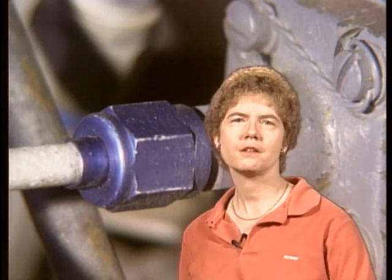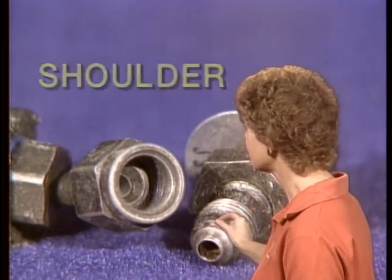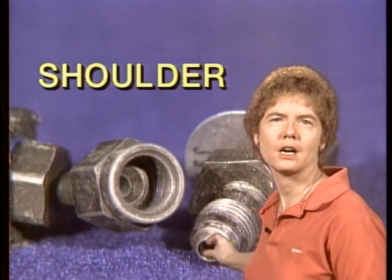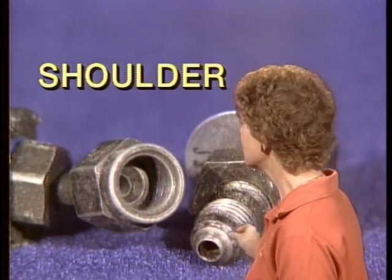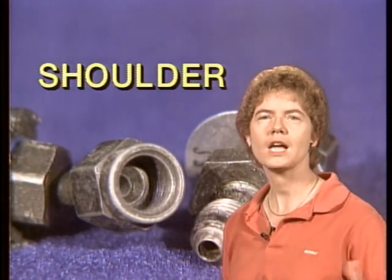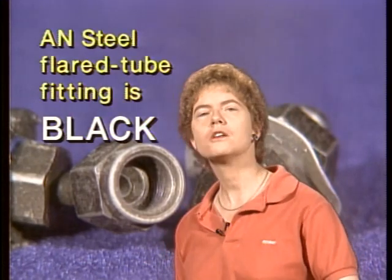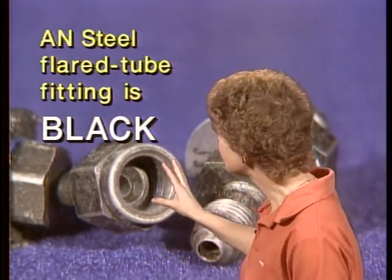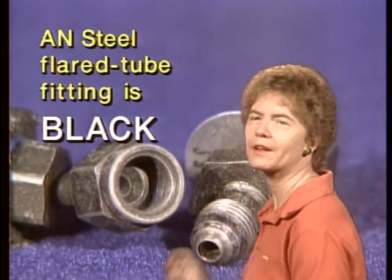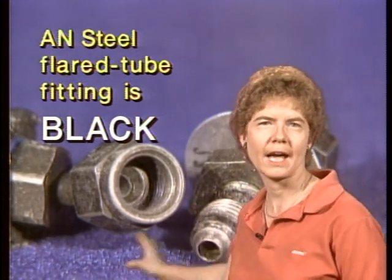Now, how do you identify AN flare fittings as opposed to AC fittings? Well, on the AN flare fittings, there is a shoulder between the threads and the flare cone, and that shoulder is what allows you to identify an AN flare fitting as opposed to an AC fitting. The AC fitting does not have the shoulder. Now, if you've got an AN flared tube fitting designed to go on steel tubing, if you have a steel fitting, the color of it is black. They are color coded, and for steel flared tubing fittings, the color code is black.